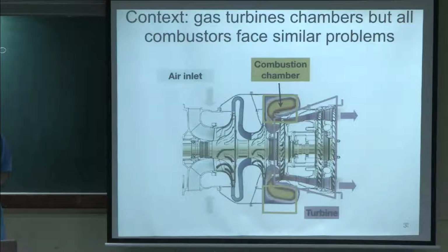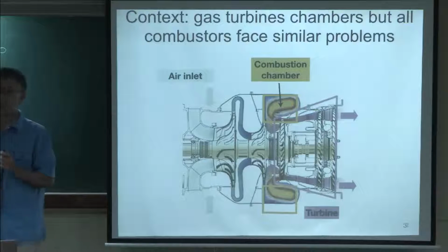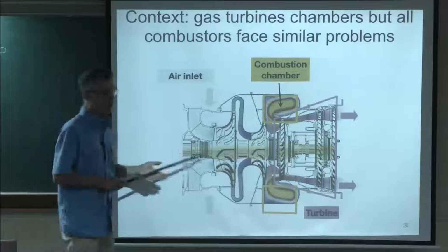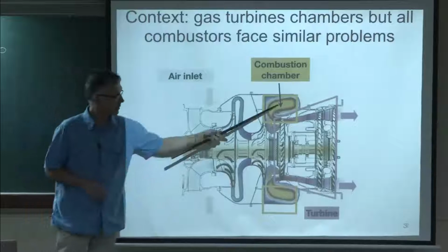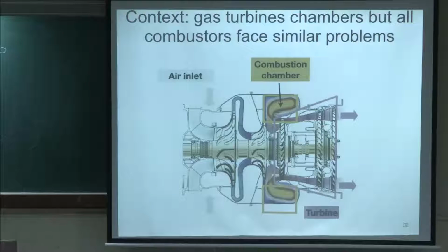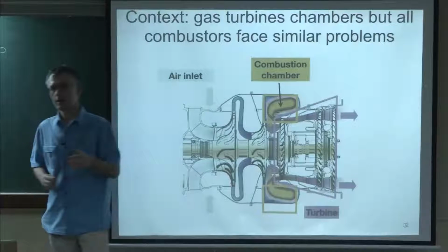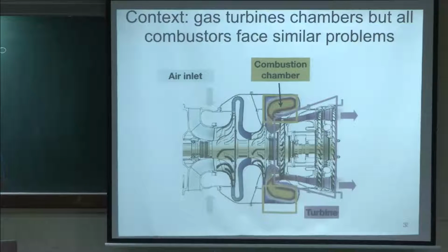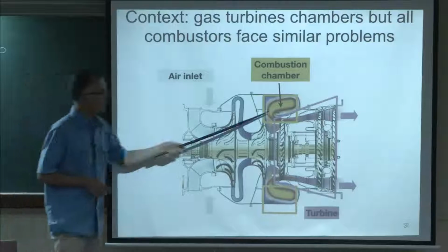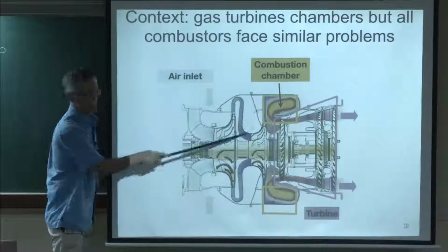There's a statement now I'd like to make about these engines, and this is also related to walls. A lot of people believe that in an engine like this one, the efficiency is controlled by the combustion chamber. Actually, it's not, because in almost all combustion chambers of that type, you burn all the fuel. Everything, 99%. So you cannot increase the efficiency of an engine like this by working on the chamber. All the efficiency is here, in the compressor.